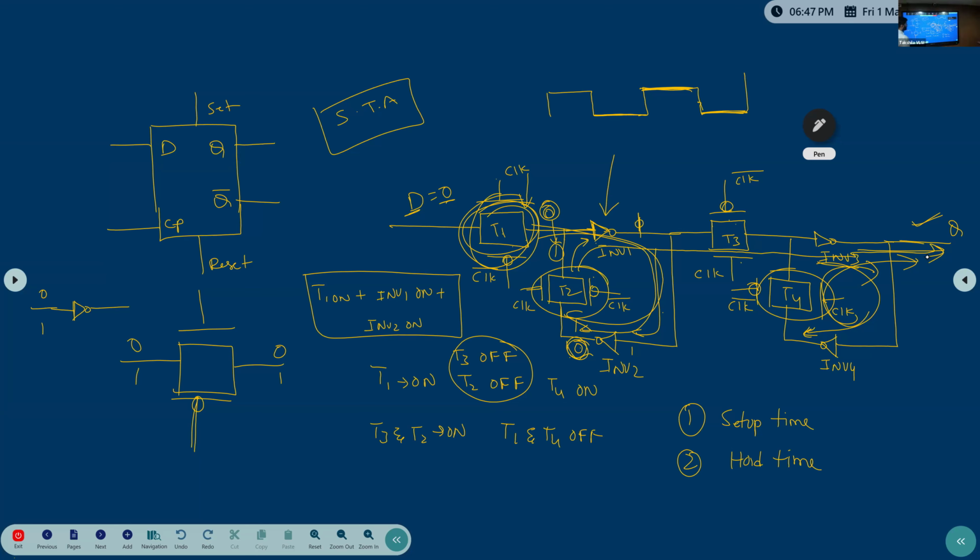First, a negative pulse will come, or a positive pulse will come, and the opposite pulse comes next time. In each condition, a few transmission gates get turned on, and the clock is made such that the data reaches the output side. So that's the reason there is no direct path. The path will be transmission gate to inverter 1 to inverter 2. After that, transmission 2 to inverter 1, transmission 3, inverter 3, and it reaches the output side. The path is divided like this.